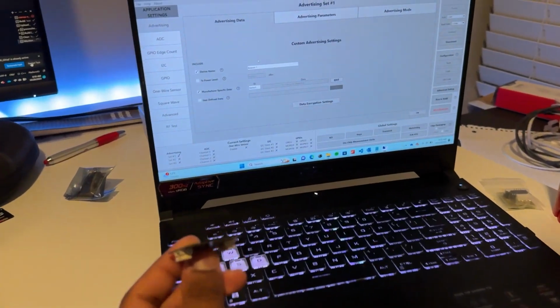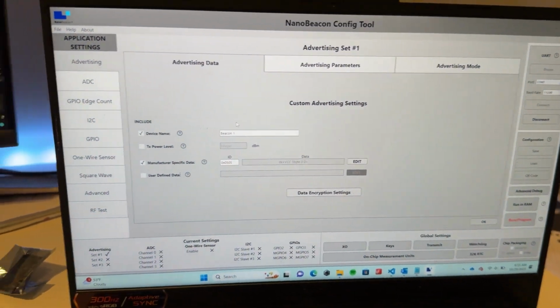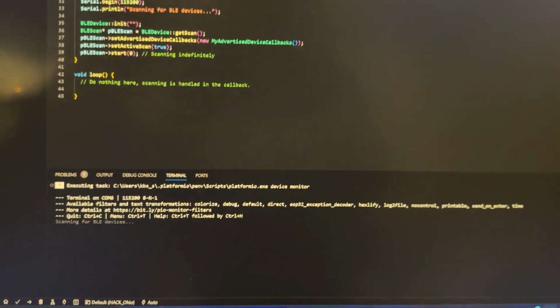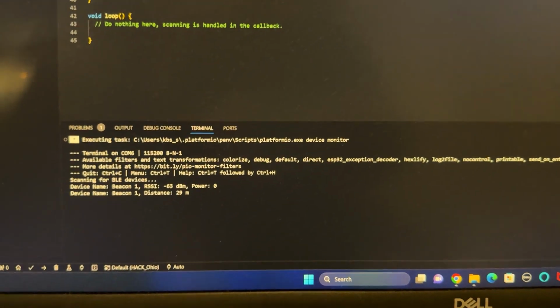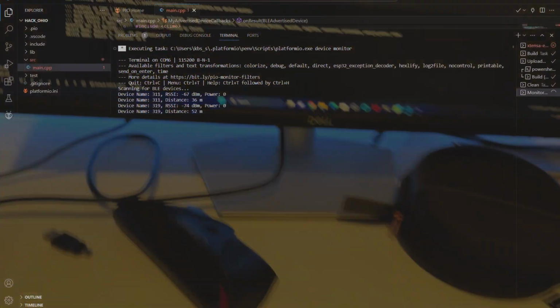Here's us showcasing the Bluetooth beacon sending packets to our ESP32 Bluetooth module. Our custom C code running on the ESP32 reads the beacon's address and the RSSI proximity.